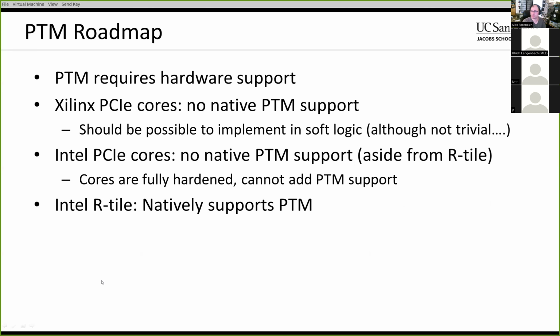So what is the roadmap for supporting PTM in Corundum? Well, PTM, like I said, requires hardware support, and that tends to be handled in hard logic on a lot of these devices. So on the Xilinx devices, as far as I'm aware, no Xilinx devices have native PTM support, unless there's something really new that got released recently that I haven't looked at in detail yet and don't have a dev board for. There's no device I'm aware of that has PTM support.